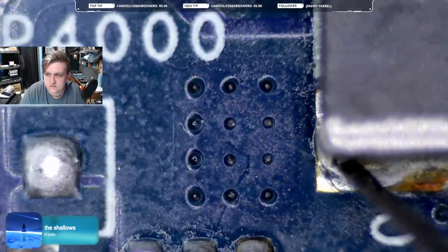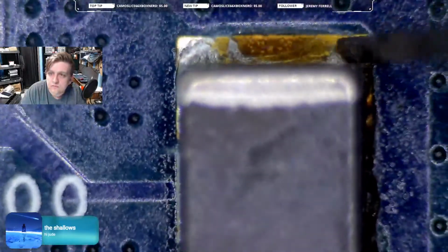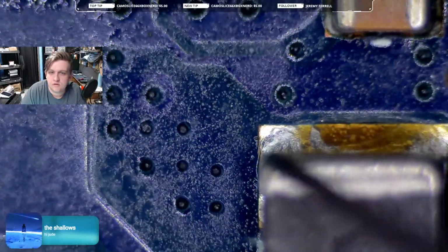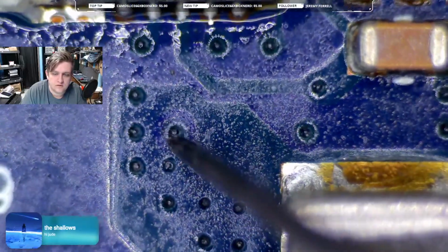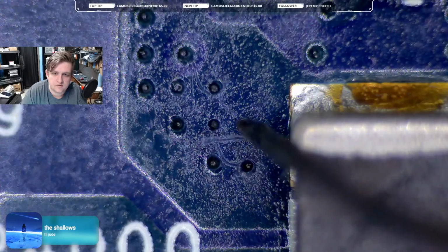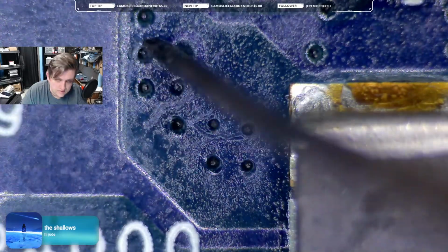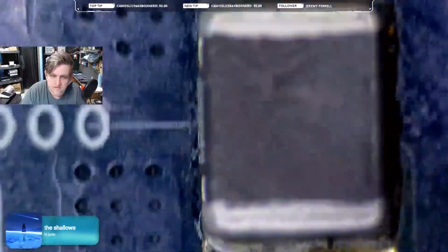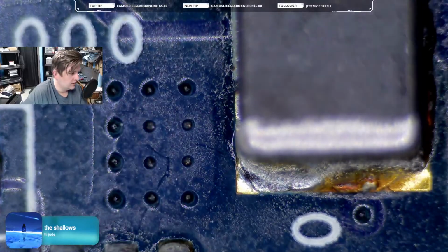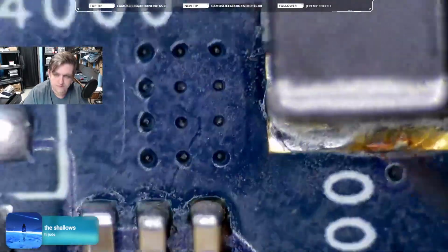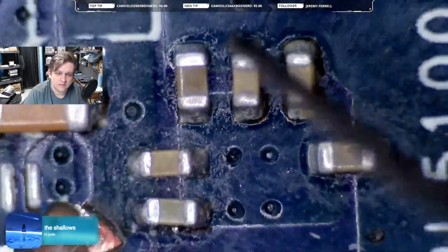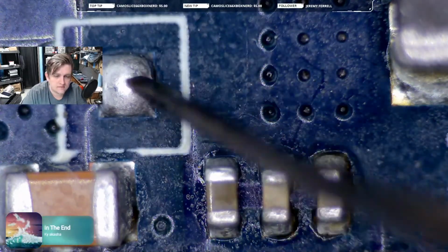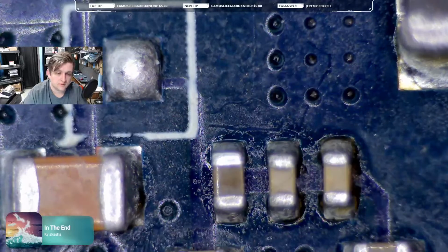And that goes to here, which is a big old inductor or something. So we're just following this trace. We're going down a rabbit hole. Oh, and it's gone. There's probably a via. There is not probably, there is vias. You can see all of them here. On the other side of this board, you can flip the board around and follow it to find out where this inline came from. But we also have the schematics, so we're not going to worry about following it on the board, we can just look at the schems. Yeah, this is a jumper pad or a test point for inline voltages.